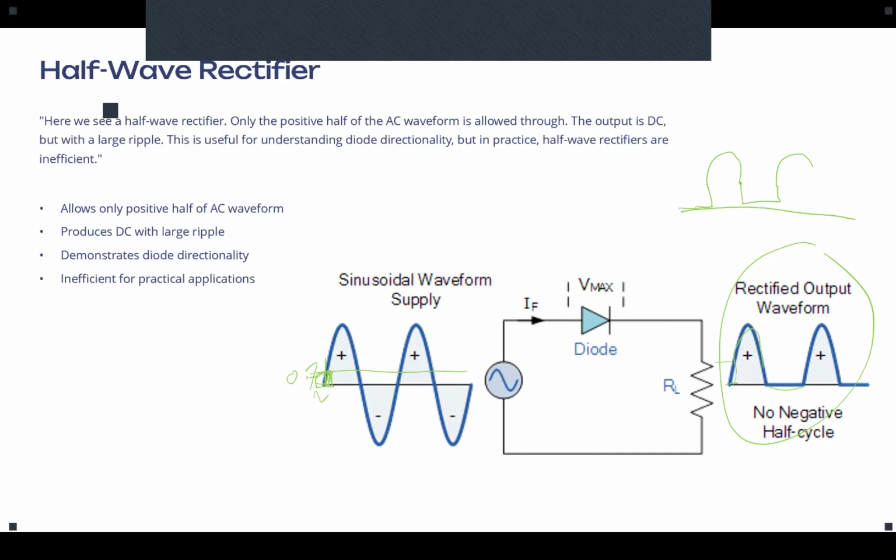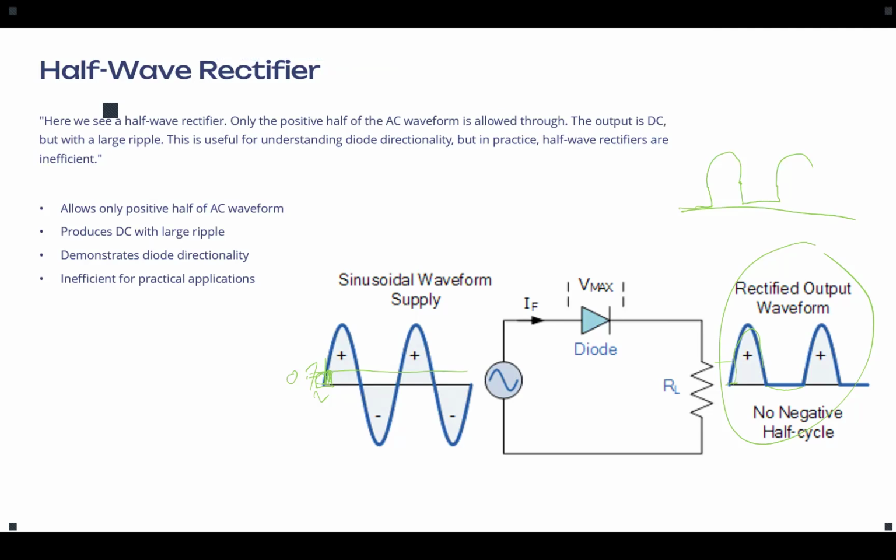Make sense? Is that clear for everyone? So that's what's going to happen in reality. Are we good? Any question about that? No? Okay. You think your peak would change? No, the peak would not change. The only thing that's happening is that the diode would start conducting when the input passes the threshold.